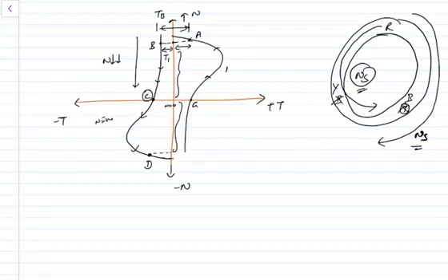Let us assume that instead of plugging, I want to use my motor in four-quadrant operation. That means you need an application where the direction should change frequently. That means you have to change from positive to negative direction and again from negative to positive direction, vice versa. In that case, what we will do is, when the motor is operating at this stable point, again reverse the terminals. That means Y and B are again reversed. When they are reversed, again the curve will become curve number 1. From this curve number 2, this becomes curve number 1. So again this point will shift to this point. Let us take it as E. Then again it will pass like this. It will come and reach point number A.